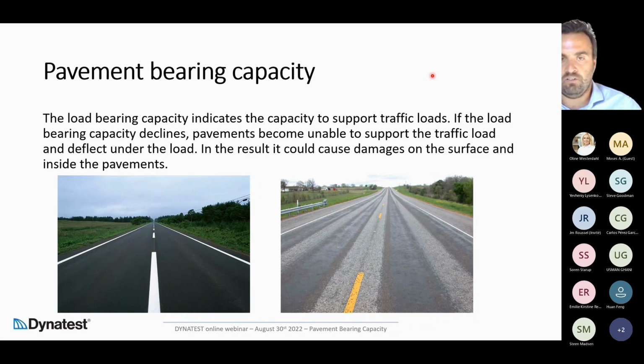So if you see the picture on the left, you see a very black new pavement. And probably most people, when they think about a road, have in mind this type of picture. But in reality, during its life, the pavement is going to change its status. It receives damage. So there is a decrease of performance that is reflected in distresses or defects on the surface. It depends on the type of defect and the entity. Of course, the road can reach a non-operative condition. So you see on the right, more or less the same road, but in bad condition because it's affected by deep rutting and probably oil spillage and other types of defects.